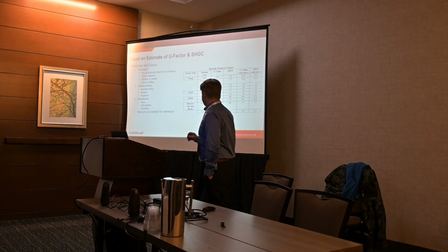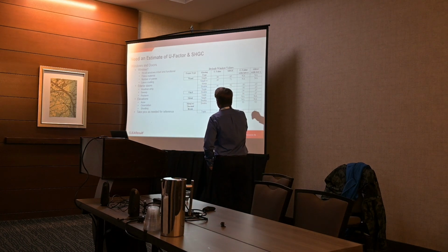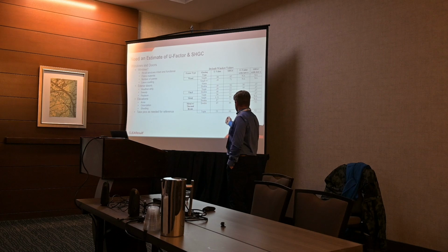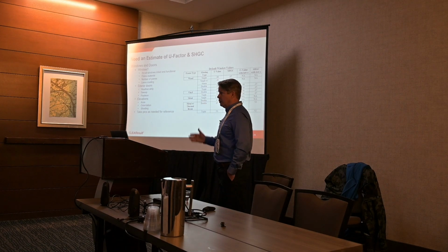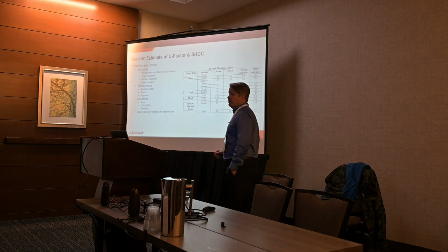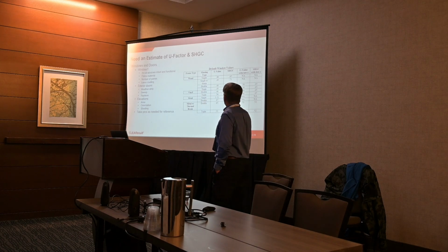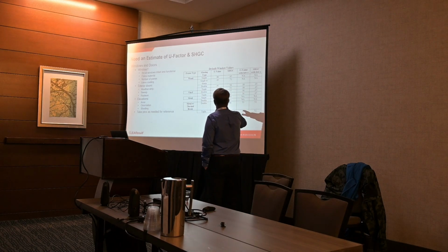If you don't have one of those, if you have, say, a double pane window, you can take an LED flashlight and shine it on the window. It's a white light, and you'll see 4 reflections of the 4 surfaces of the glass. If the 2 inner ones between the panes are a slightly different color, blue, red, yellow, it doesn't really matter what the color is, as long as it's a little bit different, then it's a low E coating, and you can tell, okay? Low E coatings significantly affect how the window performs.